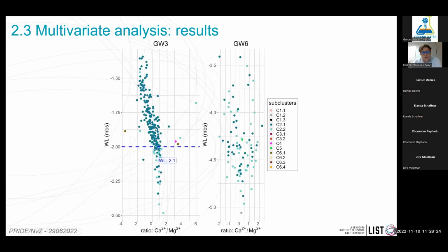This is just interesting behavior from the secondary plateau, because there's such a shallow weathered front, and it's highly fractured. It also has a different type of vegetation that we see has a lot higher input of nitrates and chloride. So you can definitely see that it's chemically really not altered. It's just recharged, runs through the fractures, and is discharged into the stream.